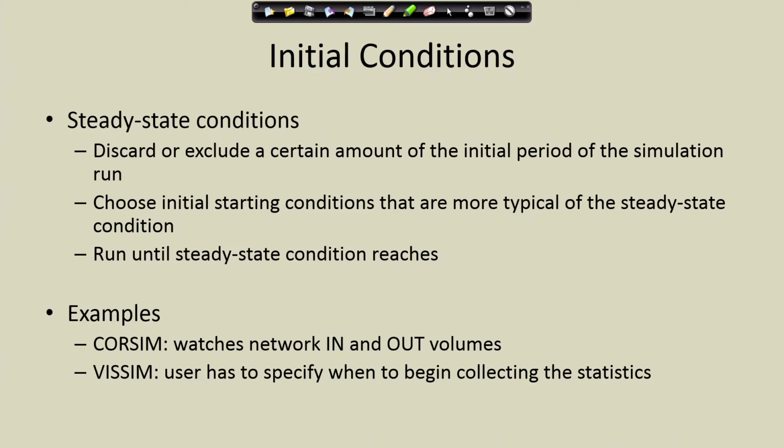Is there any percentage range of precision so that as a modeler we can say that our model is actually mimicking the real scenario? Yes and no. The planners are very generous about it. It's called GEH, I believe. If the difference is within about 30%, they seem okay with it. But if you are doing different performance measures, you'll have to justify why this amount of difference is acceptable.